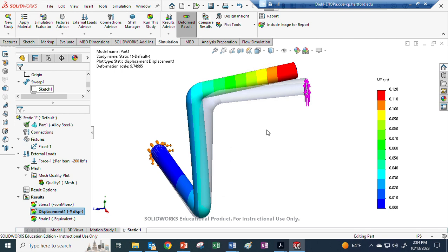So anyway, I think that's enough for today. Does that help? The kind of consolidation of some of the stuff. But also I think it was important to see, hey, I got something that didn't make sense on the piece of paper, didn't match with the FEA, and then I tried to resolve it. I got to tell you how important that is. That's why you do the thing on paper to check the FEA, and that's why FEA is a good tool to use hand in hand with doing hand calculations. It can't replace it, not 100%.